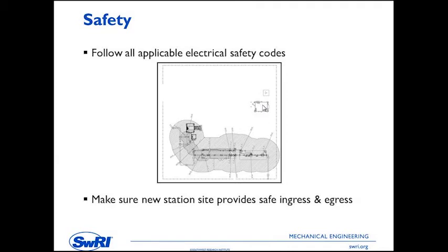One thing, if we go back to the site plan here and we look at what might happen with this particular building, if there's a chromatograph building, you're bringing a hazardous gas into the analyzer room, and you have an analyzer and controller that are two portions of this chromatograph. There is not a particular NEC requirement to address the requirements for that particular build-out in the building.